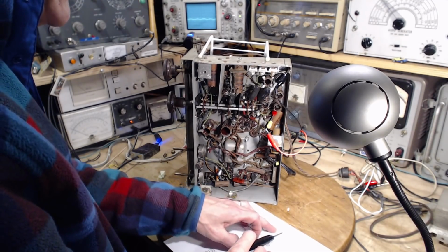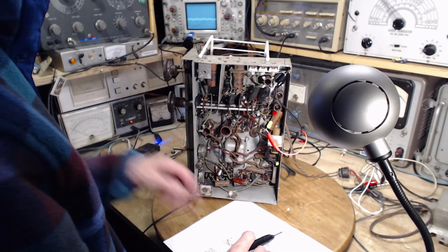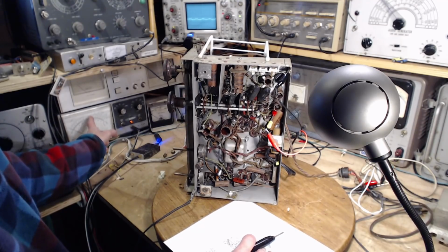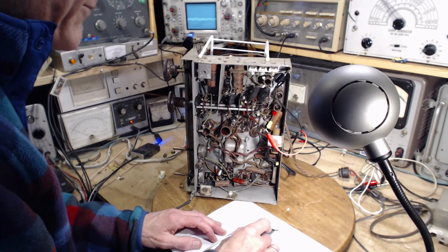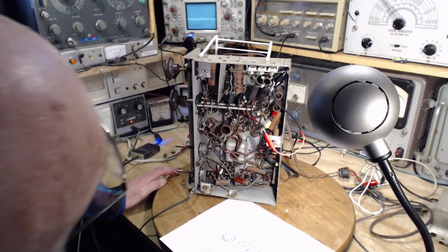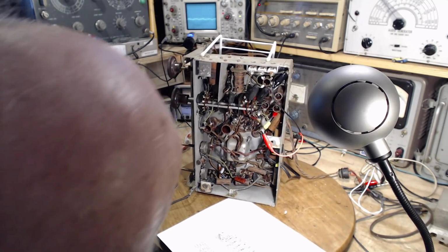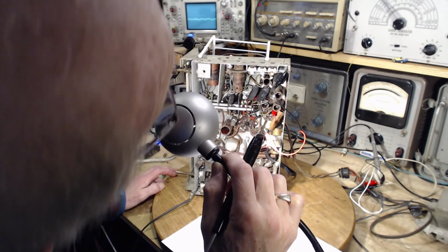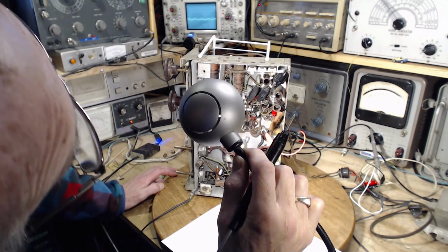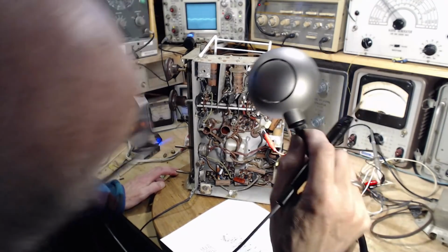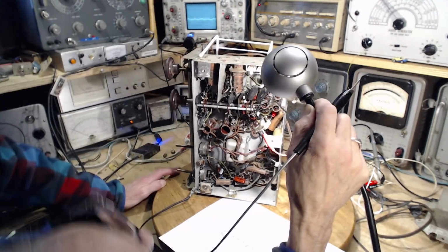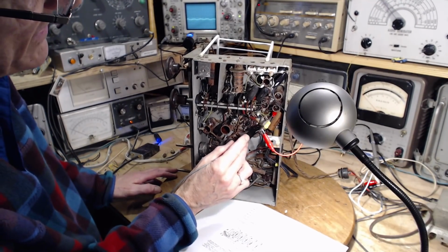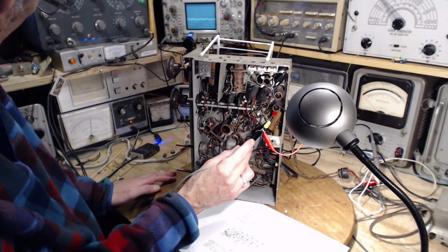So that's a 6SK, and then the screen grid should be 82 volts. I'm going to go down to the 150 volt scale, 82 volts, so right about here. Now can I get to that pin? Pin number 6. I think the answer is no. I can't really get to it. Oh, wait a minute. 876. So on that great big wire, my great big wire going way over here, I believe this is the screen here. Right on the money.